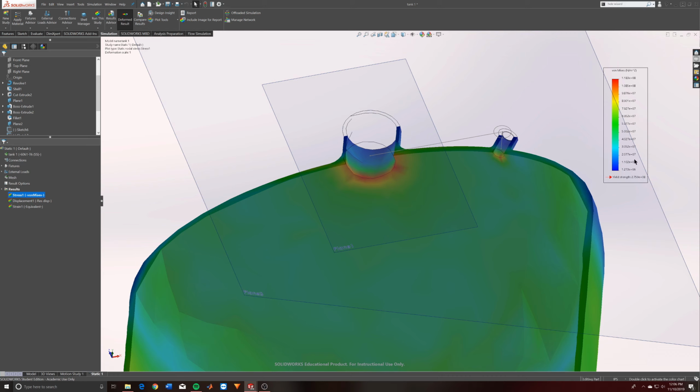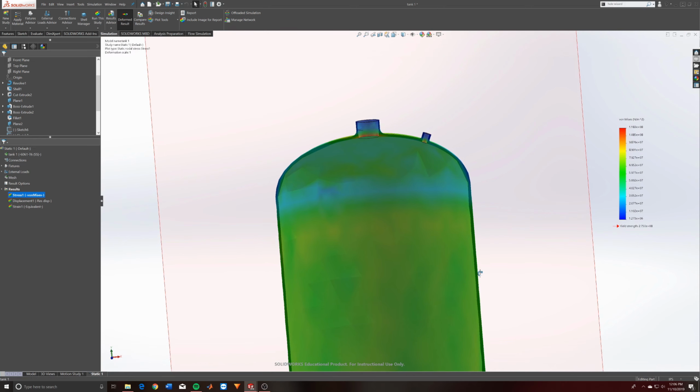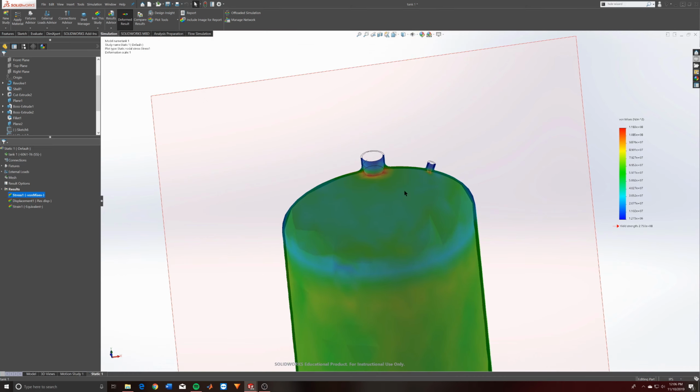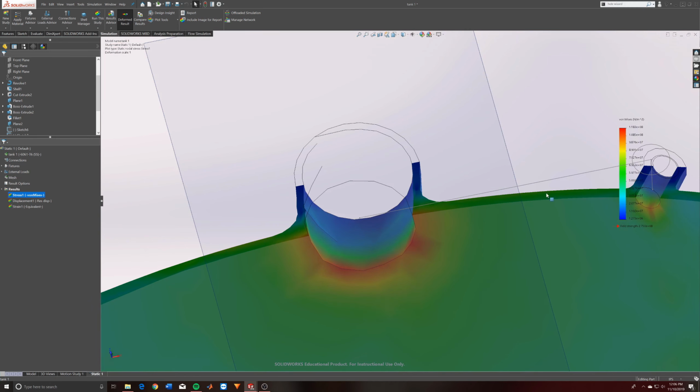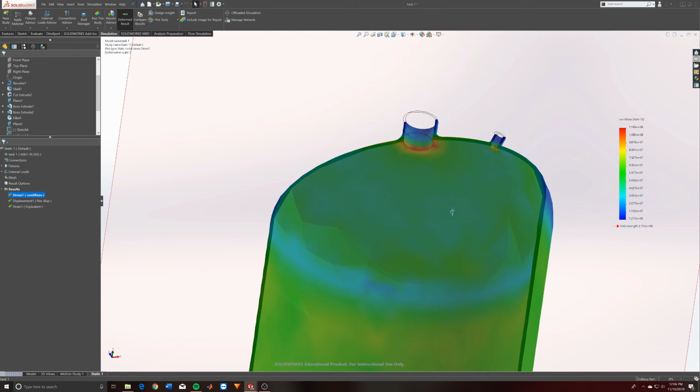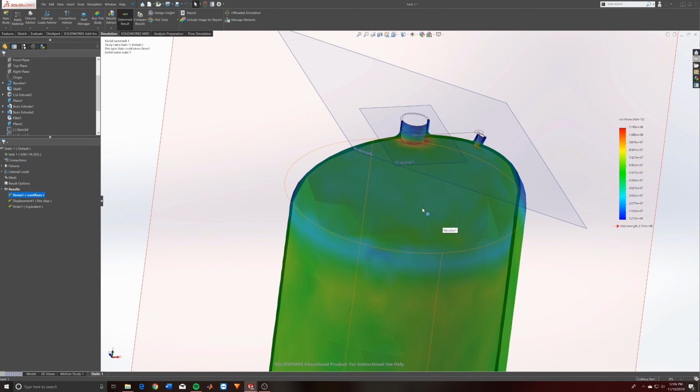which means we get 118 MPa, and then our yield stress of the material is 275 MPa. So we're way below our yield stress of the material, which is aluminum 6061. So essentially, for a tank at 0.1875 inches thick with 20 bar pressure, we're getting a tank that'll withstand almost twice the amount that we need. So we could probably go up to 40 bar instead of 20 bar, and this tank would still be fine.